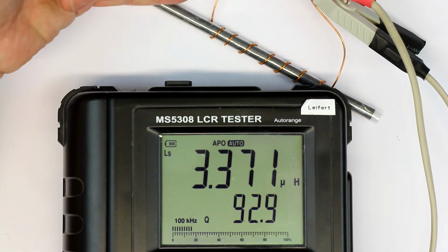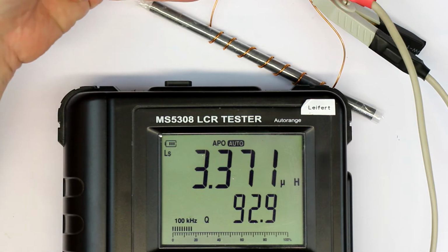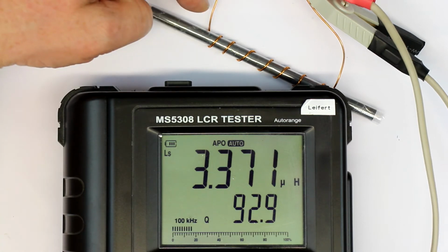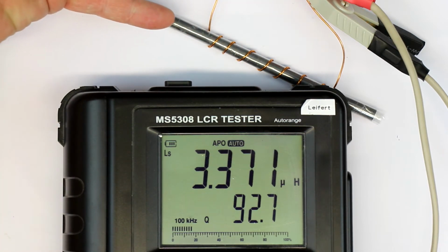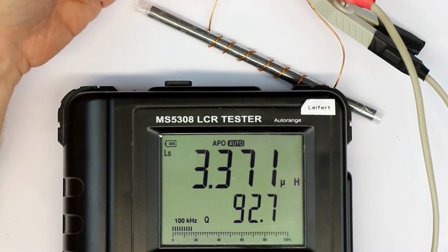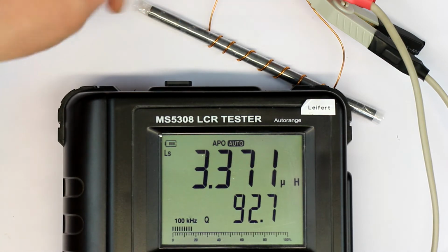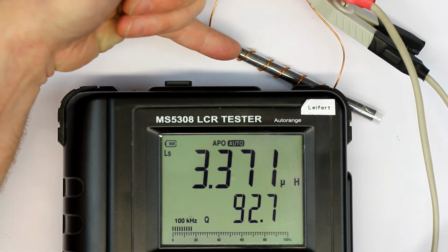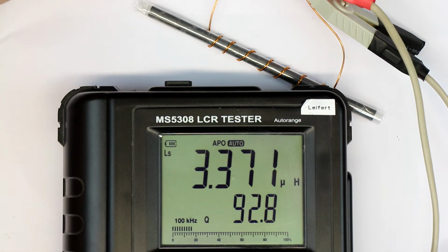And of course, what you notice is the result of what we learned in the other 2 videos. At the higher frequencies, you have to use either very thick copper wire and not Litz wire anymore, or even copper tubing. Now the space here wouldn't be sufficient to use copper tubing, so I've used, I think, 1 millimeter or 1.5 millimeter copper wire, and there is a great separation between the turns. That is just to minimize proximity effect.